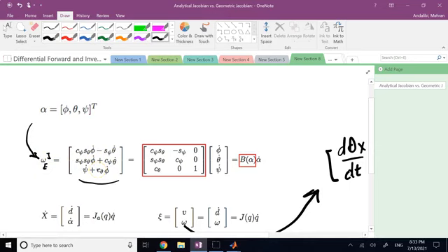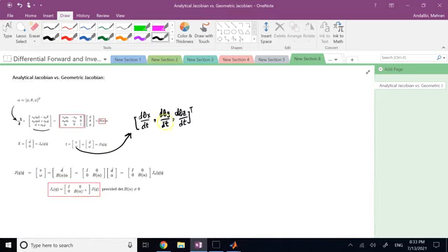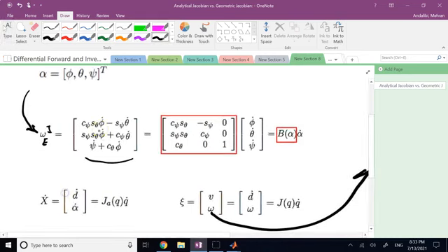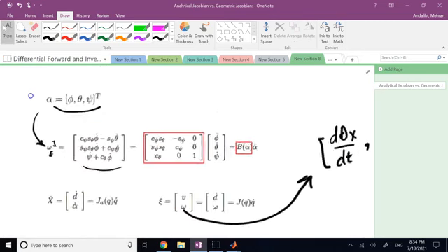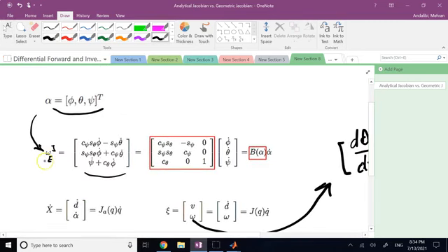So you see, it's not as simple as the time derivative of three angles. Not only the time derivatives of the angles, phi dot, theta dot, psi dot, are involved, there are sine and cosine of the angles also involved, because these guys are intrinsic angles. They are with respect to the current axis. Not all of them are absolute angles. Okay, so for that reason, your omega is different.